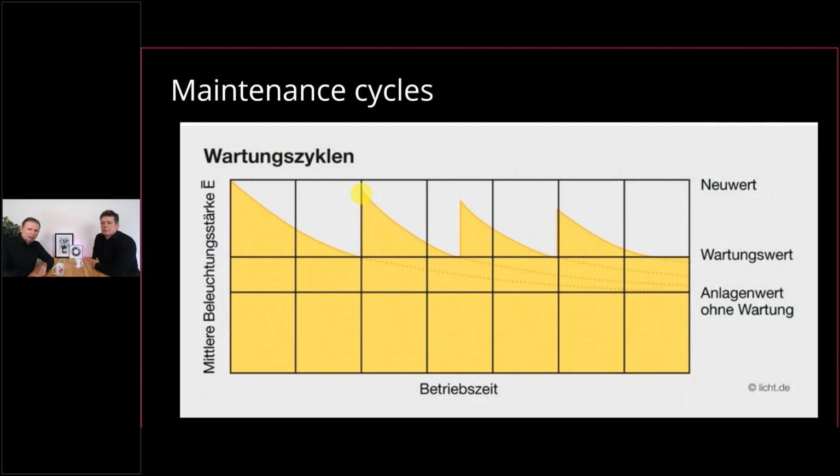Most of it is about the lamp, to re-enable the lamp to put out the lumens again. So by replacing the lamp, in old times, or in new times with LEDs, exchanging LED modules, or even exchanging the complete luminaire after a certain time. This cycle also depends on what you have installed in which situation. If you do not do any maintenance, you're just dropping down and dropping down at some point to zero. Even with LEDs, it will decrease to zero, depending on the usage and how long it runs. The whole maintenance story is just about dealing with the loss of illumination over the years.